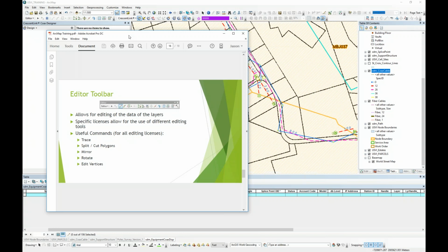You also, if you're going to do the dB loss correctly, you need to have the type of fiber panels in the CO, because the older stuff has a way higher loss. You need the splitter values. You also need the input requirements for the ONTs. Correct. Yes.